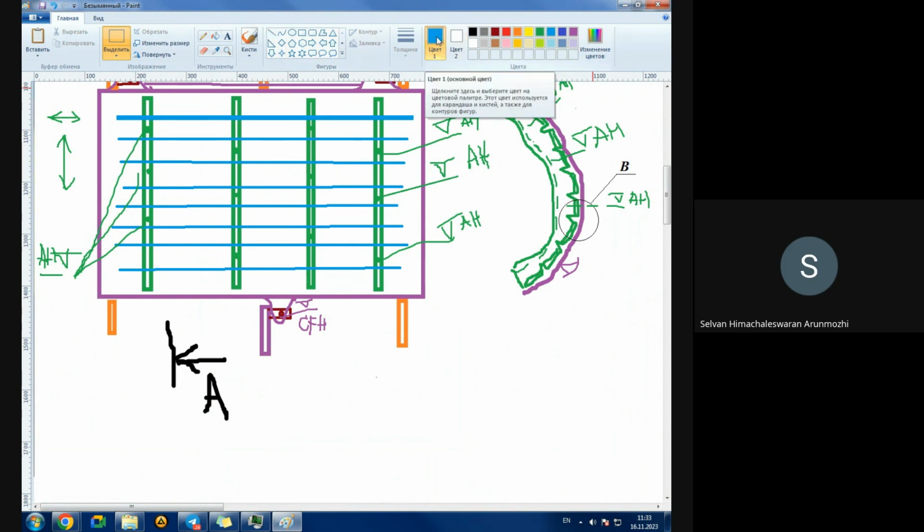But you do remember that each next hole increases the cost of work. It doesn't necessarily result in increased accuracy. On the contrary, the more holes, the more probability that some of them do not coincide. But when you just locate the parts during the locating procedure, an additional extra hole would be better for the stiffness of your structure, because you insert one more clamp into this hole. Let it be 4 holes in each stringer.